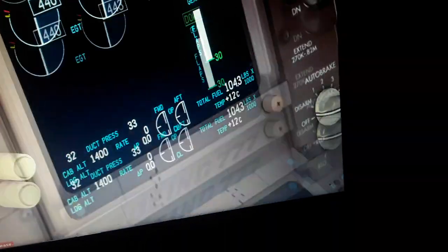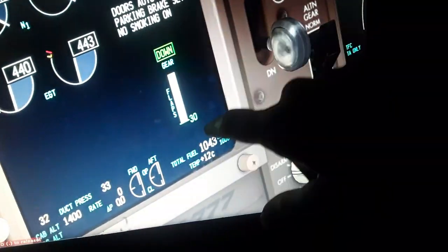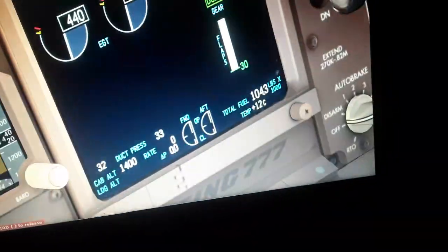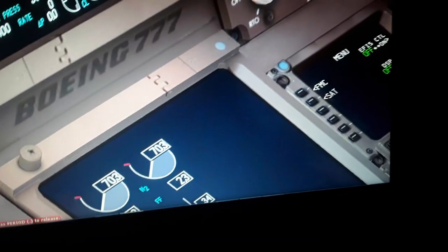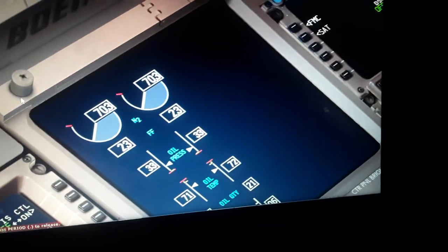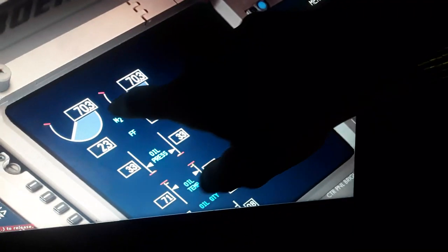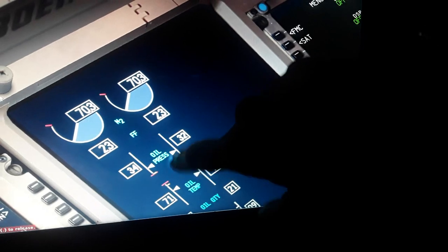Some other information not related to the engines over here usually, and landing gear, flaps and total fuel. You can see the Boeing 777 here, the mark of the airplane, the N2, which is the high speed, high pressure compressor stage of the turbofan turbojet engine. The fuel flow per engine per hour, the oil pressure, oil temperature, oil quantity and the vibration of the N2 stage of the engine.